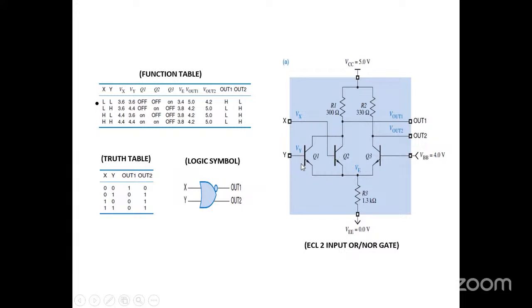So this is on in the differential configuration. In this differential configuration you will be getting two outputs with respect to the ground, with respect to each other, the output will be taken across the collectors. And this is how the operational amplifier configuration is also made up of using this type of circuits only. So there also two inputs and one output will be there. So this is an unbalanced, this is a balanced output of the differential amplifier that we can get.